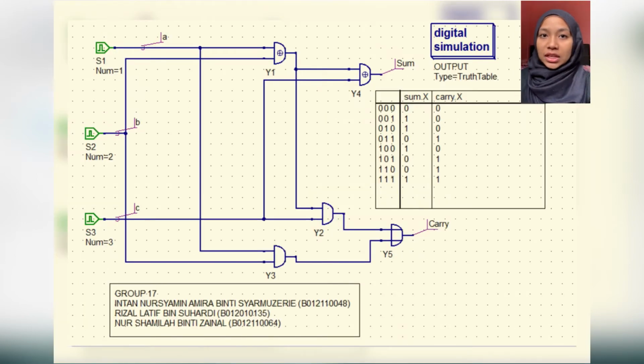A full adder is a combinational logic circuit which performs addition on 3 bits and produces 2 outputs, a sum and a carry. As we have seen that the half adder cannot respond to 3 inputs, and hence the full adder is used to add 3 digits at a time. It consists of 3 inputs, of which 2 are input variables representing the 2 significant bits to be added, whereas the third input terminal is the carry from the previous addition. The 2 outputs are a sum and carry outputs.